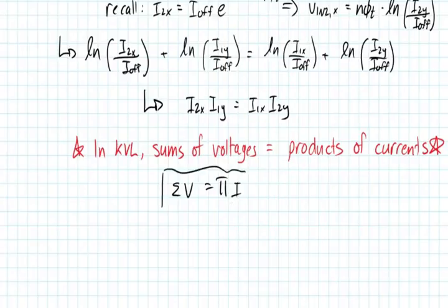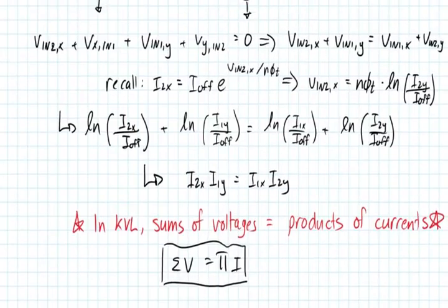Okay, so that's a nice, cool thing that is very useful in the context of, let's say, we have some analog signal that we're trying to capture, and we'd like to do a little bit of pre-processing of that analog signal. Well, what this translinear type of circuit allows us to do is some amount of analog processing. We can do multiplication, we can do addition by basically just summing current nodes together. We can multiply by fixed coefficients. So you can imagine you can build some sort of basic analog computer using the techniques shown here.